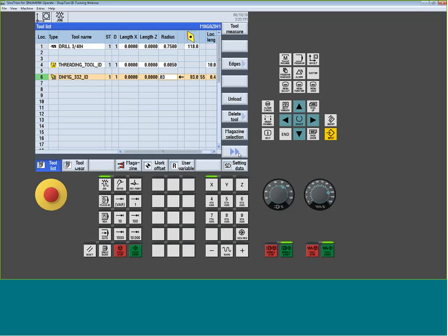So we're going to have a 0.315 nose radius. And now we have our relief angle. So since it's an ID tool, I don't have to spin everything around. Everything bases off of my 0, and now it's looking at it from the other direction. So the same rules apply. If I have a 90-degree value, it's going to stand the tool straight up, so as if it has no relief. Now, as I increase it, if I have 5 degrees, I can add 5 degrees to it.